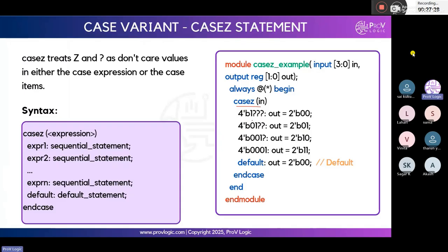Okay, but we declare it as a question mark. 1 question mark question mark question mark. That means whatever values are generated, instead of the question mark it will generate either 0 or 1. So here, with 3 question marks, if all generate 0, or 0 1 0, or 1 1 0, whatever the possible values are, you can generate all possible values. We'll get 8 possible values in these 3 bits. So for all of those, we are assigning 0 0.